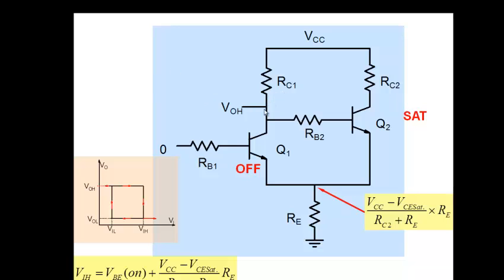And as this voltage starts to drop, what does it do to Q2? This is the voltage which is turning Q2 on. So as this voltage starts to drop, it tries to switch off Q2, right? That's the direction in which it is going. So as this transistor starts to turn on, this voltage drops, and this transistor begins to switch off, and the current here drops. Now, the current in Q2 is what is causing this particular voltage here. So what happens to this voltage then? This voltage begins to drop.